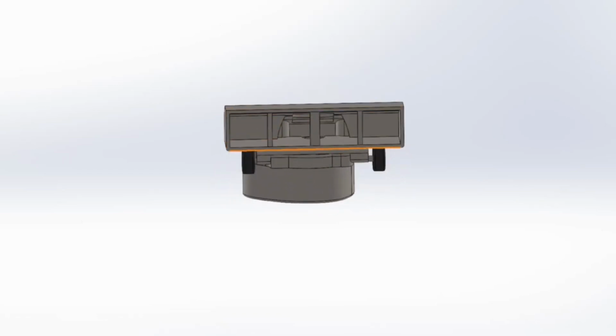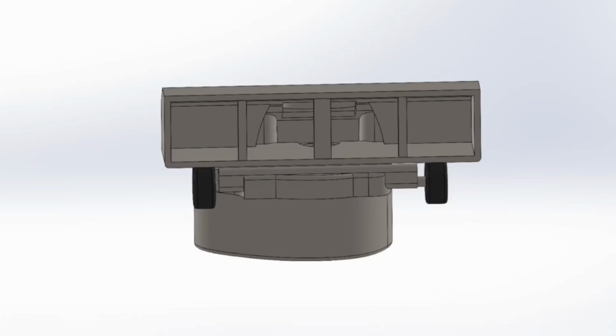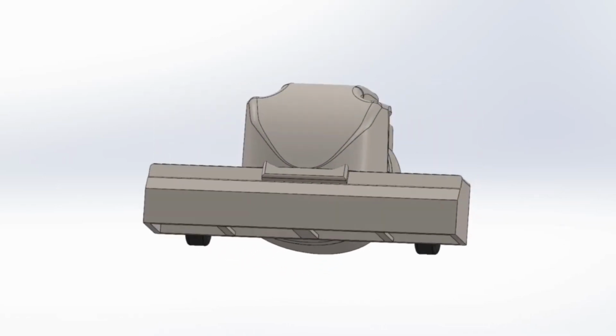You can see that the area is pretty large, and then the fluid will travel towards the impeller, which is this hole right here. What you'll notice is that the area decreases a lot, and we know from the mass flow rate equation that when area decreases, the velocity of the fluid increases. This hole in the back will lead into the impeller, which I'll show you right now.